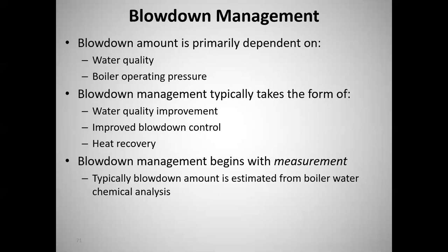Yeah, a softener is kind of the first stage of water treatment. That's what low pressure systems have. That's what Tech has. You go down there into the boiler house and they've got these two big circular tanks with some kind of water softeners in there, and it pulls out a lot of that stuff. But they're only running 100, max 110 pounds of pressure, so their requirements are not that severe. But you get up to 400, 600, 800, 1,000, and you've got to get cleaner and purer. I've got a slide in here that gives the different concentrations that are acceptable at different pressures, and you see the water has to get better and better as the pressure goes up.